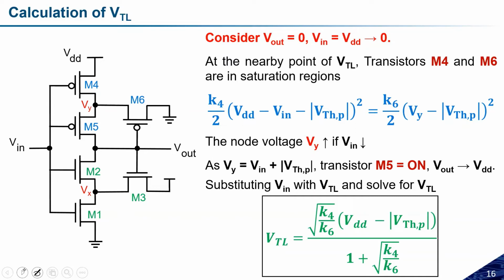Now let us talk about why we need the Schmitt trigger circuit. Schmitt trigger circuits are basically giving the sharp transition, and they can make a transition only if there is sufficient change in the input. So what happens if there is some noise present in the input which is fluctuating? If there is some fluctuating noise present in the input, the Schmitt trigger will not provide the output based on the fluctuation. It will maintain the same logic. So to eliminate the noises, electromagnetic noises, we can utilize this Schmitt trigger circuit.